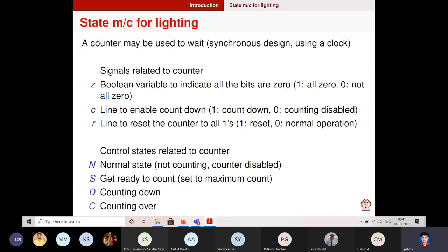Okay, so let us come back to the synchronous counter. Let's say we represent the counter as follows. For example, in the stopwatch case, you are saying that it counts from 1 to 5,000. So I can represent 1 to 5,000 in the decimal way like this. Say 1 I represent by 4 digits: 0001, 0002, 0003, and then after 9 it will become 0010, then 0011 and so on. So you see the digits are increasing by 1. First the least significant, then the second least significant. These digits are increasing by 1 as the counter changes state.